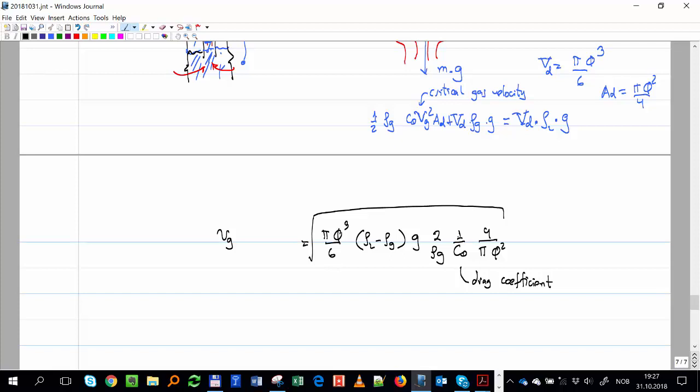If I express the drag force with that expression, I measure all the rest: the density of the fluid, the velocity of the gas, the area. Then I can find a correlation for that drag coefficient, and that's usually available for spheres. Some people did that work a long time ago.